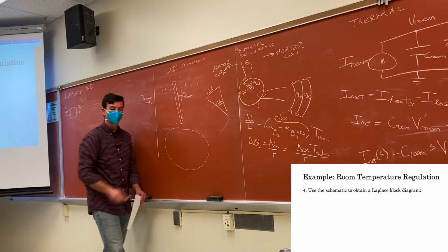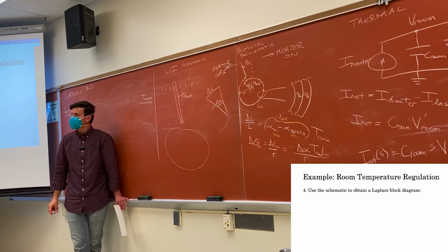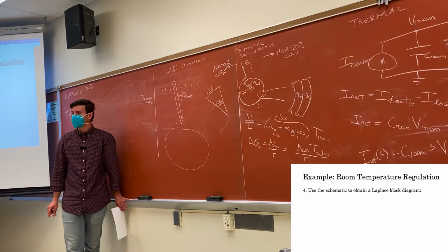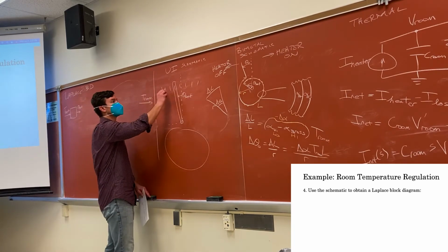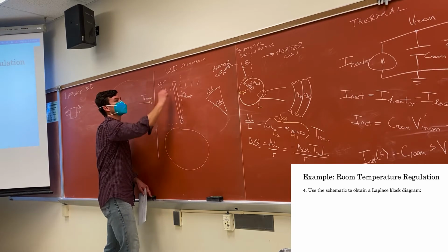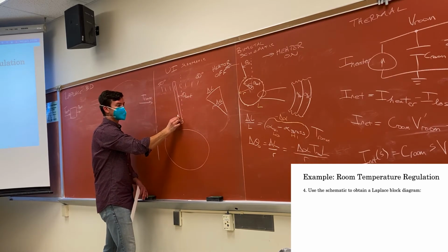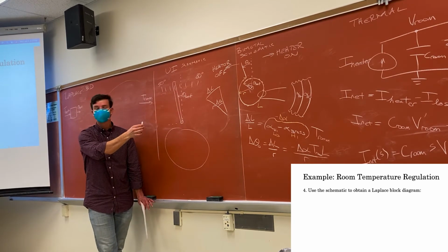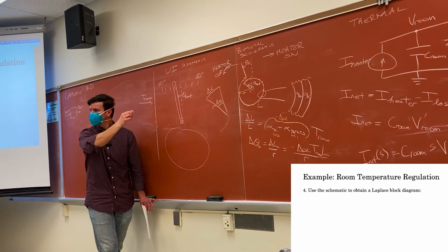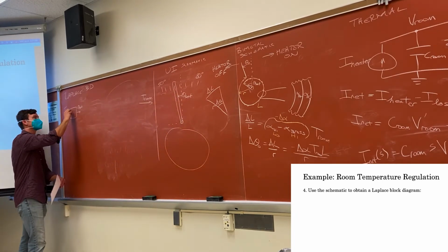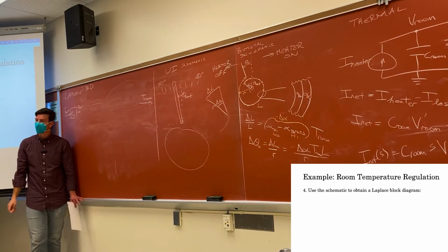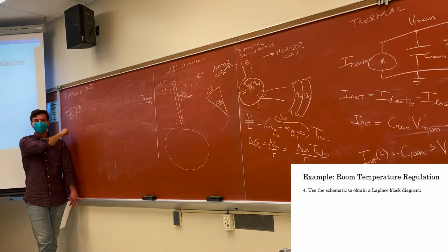That would be the math that goes right here. I would really like it to be linear. I would really like it to be a scaling factor. The way that you could check this would be if this is, I think, 50 degrees and this was 80 degrees, just make sure that if these are evenly spaced, these angles are evenly spaced. And as long as you make these demarcations properly, that'll be true. So they're going to use some scaling factor that changes the temperature in Fahrenheit to an angle.